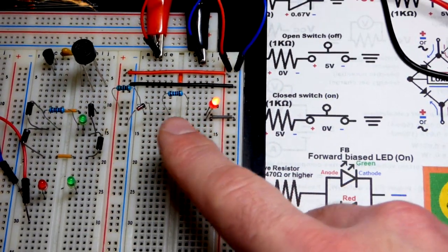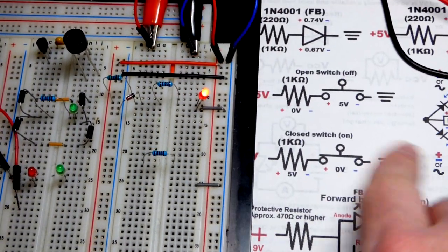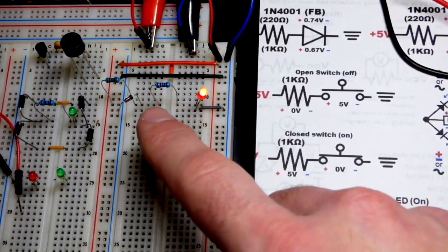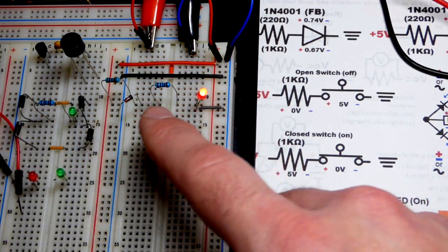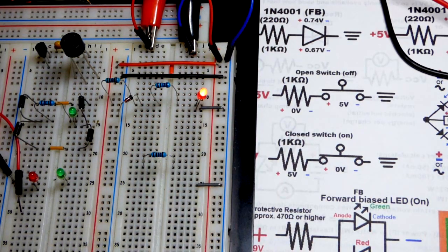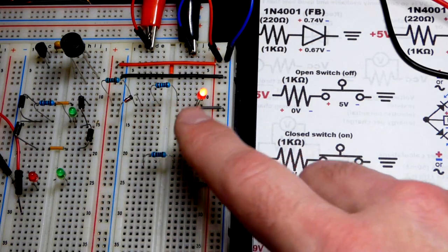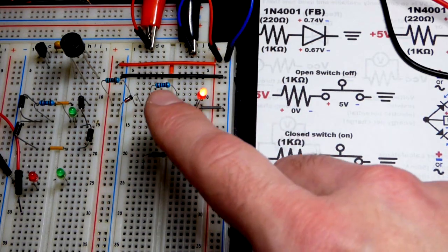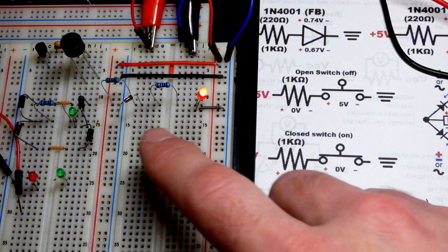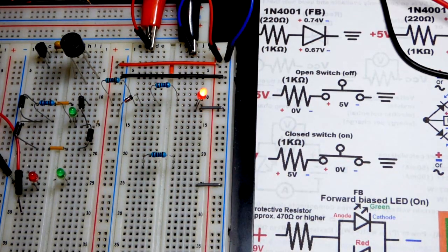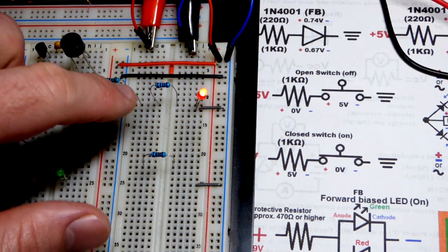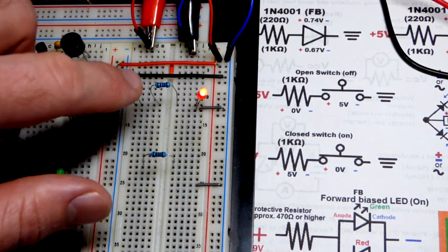And then the Zener diode, there's a lot of circuits where you want to set a voltage, and usually you don't power the load with that. That'll be transistors. We'll look at that. You can set a voltage to a transistor, and the transistor will do a better job of holding that voltage. But in any case, the Zener diode is a really good, really simple way, if you have a bunch of values, to set a specific voltage at a point.